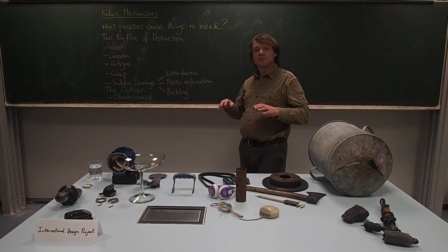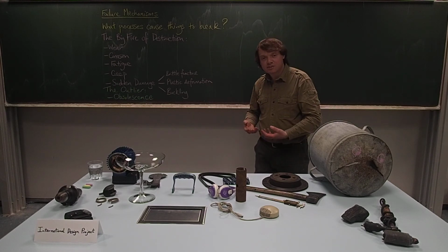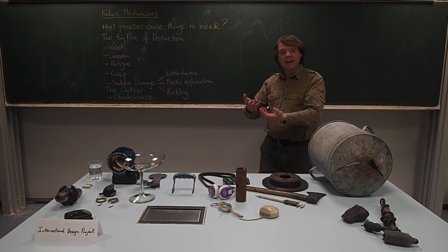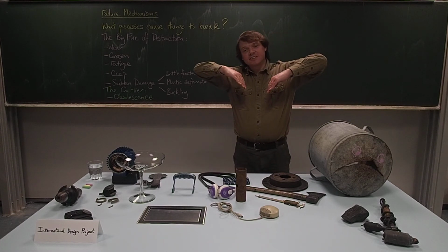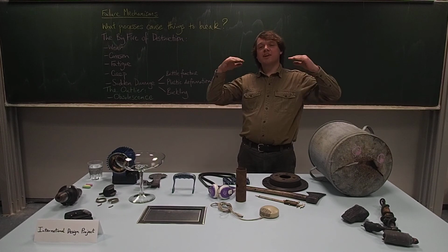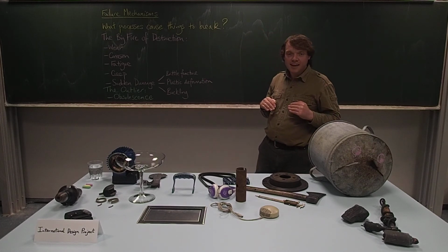What they tend to do is have some mechanism which splashes the oil over the gears or lifts up the oil and allows it to trickle back over the gears, and inside they have little deflector plates which then bring the oil back into the sump and keep it away from the joints in the case.